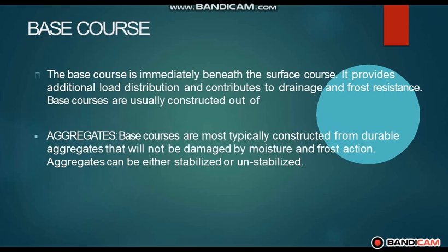Base course. The base course is immediately beneath the surface course. It provides additional load distribution and contributes to drainage and frost resistance. Base courses are usually constructed out of aggregates. Base courses are most typically constructed from durable aggregates that will not be damaged by moisture and frost action. Aggregates can be either stabilized or unstabilized.